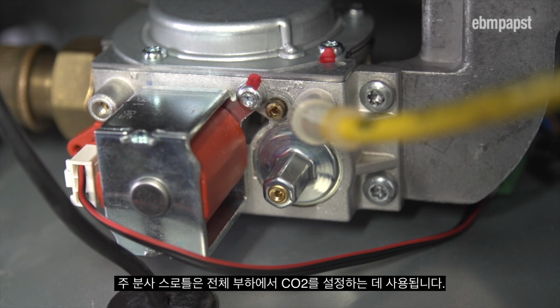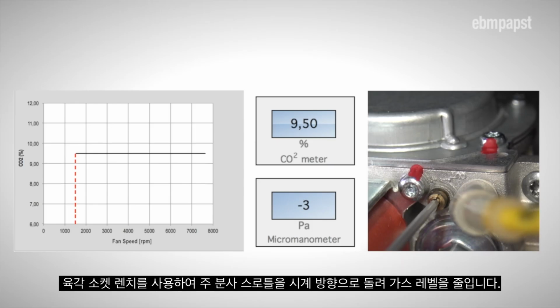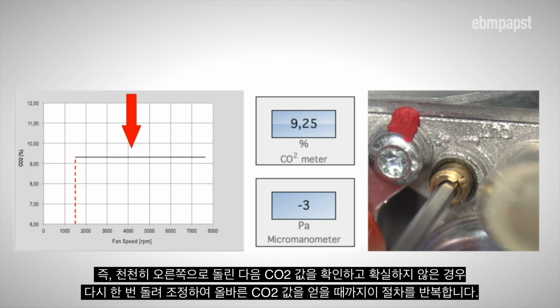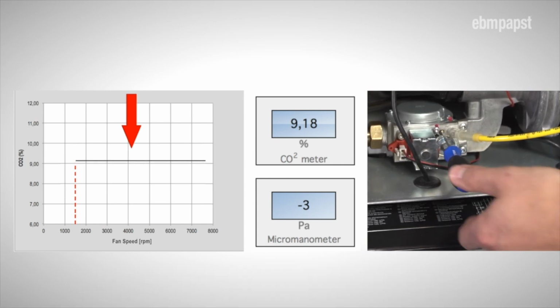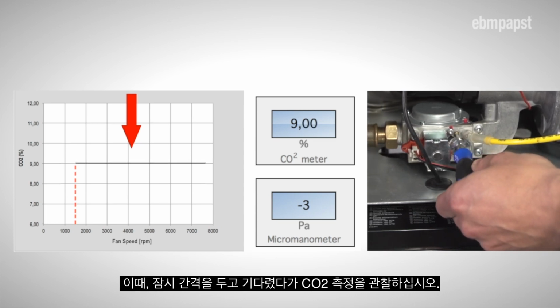The main injection throttle is used to set the CO2 at full load. Employing a hexagon socket wrench, the main injection throttle is turned in clockwise direction to reduce the gas level. This means turn slowly to the right, then check the CO2 value, and, if in doubt, adjust again by giving it another turn. Repeat this procedure until the correct CO2 value is obtained. When doing so, wait briefly and observe the CO2 measurement.